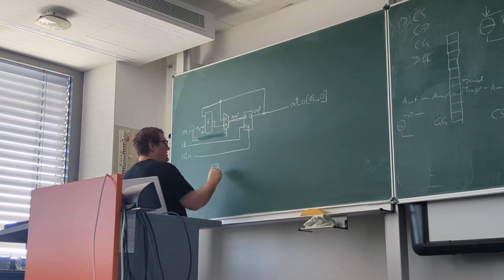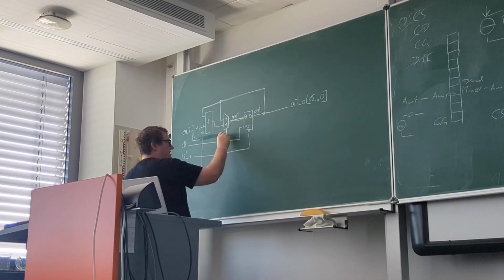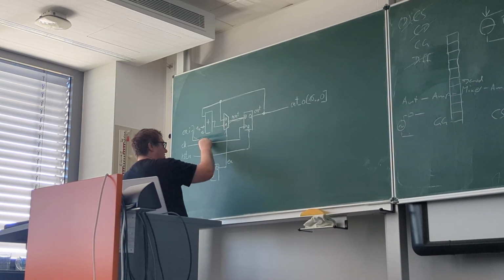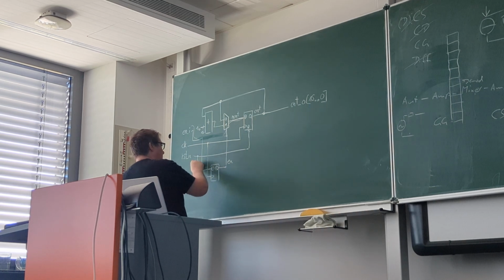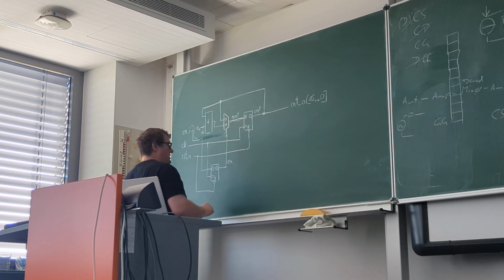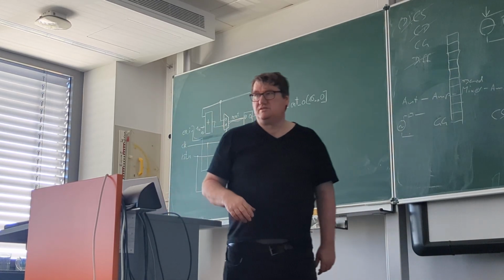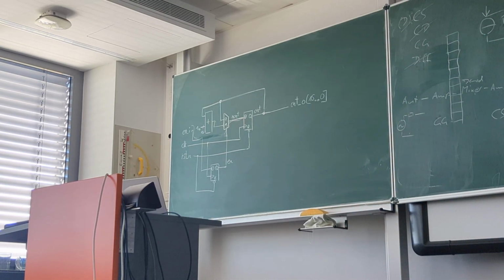The enable input goes here, and we have a signal called enable, and this is connected to the clock, and if you want, also the asynchronous reset. So how do we need to change the code to have that pipeline register introduced?